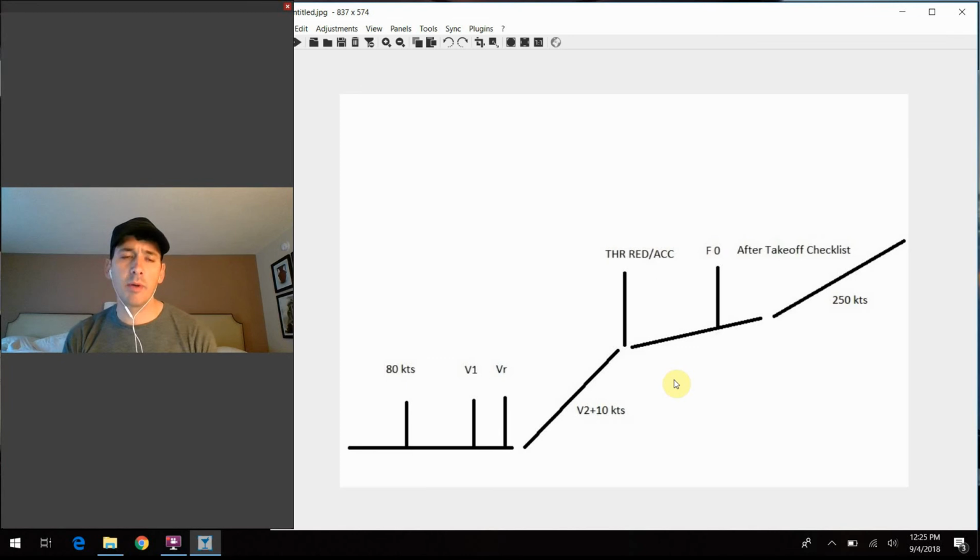That's why we're pretty much religious about verifying the runway heading when we roll out there, so we make sure we're taking off on the right runway. So once again, I'm pilot flying. I'm going to say, runway heading 014. Monitoring pilot's going to say checked, and that's our verification that we both agree. So we'll wait, of course, for the tower to assign us the takeoff instruction.